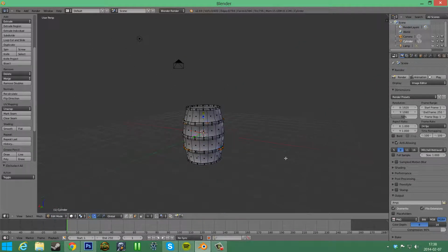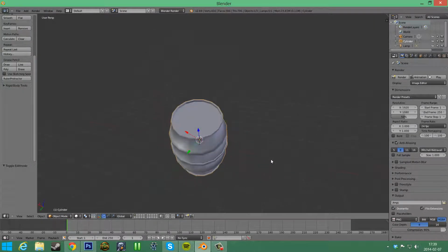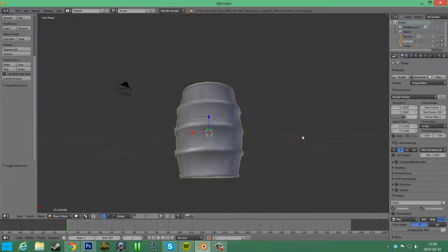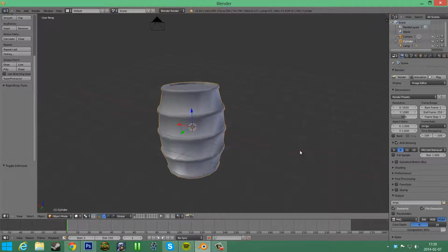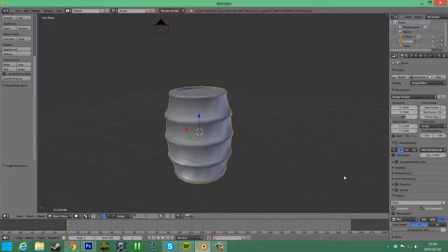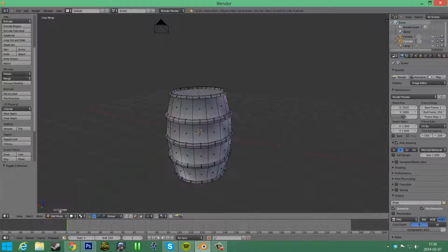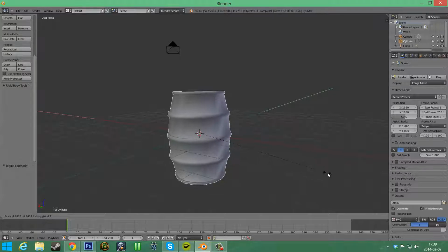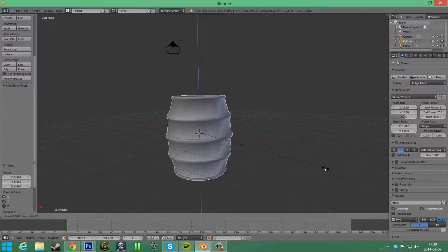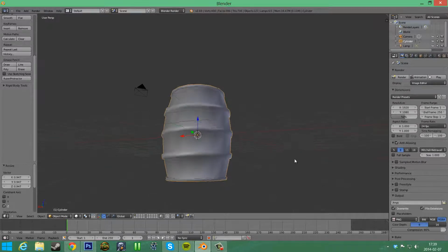So I actually think we should scale the whole thing a bit to the center, because I think it's a bit fat. So what we could do, press S in object mode. You can also press here to change between edit mode and object mode, and then you press S and Shift S so you don't scale the height. So now we could do a little bit like this, maybe only scale the height like that.